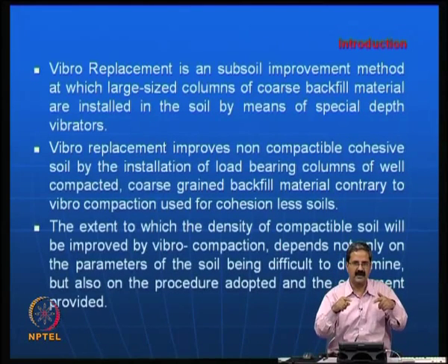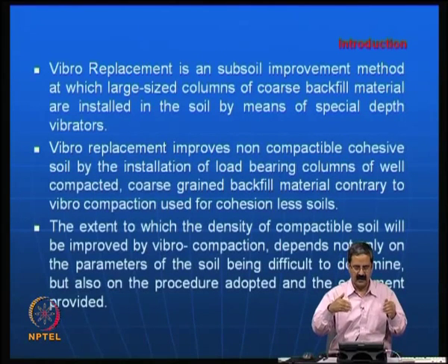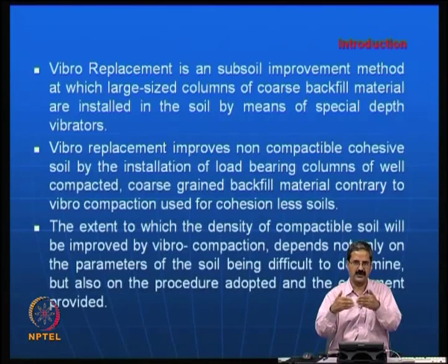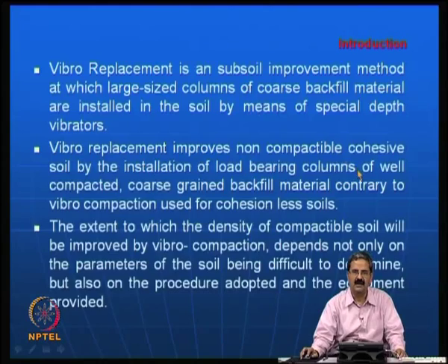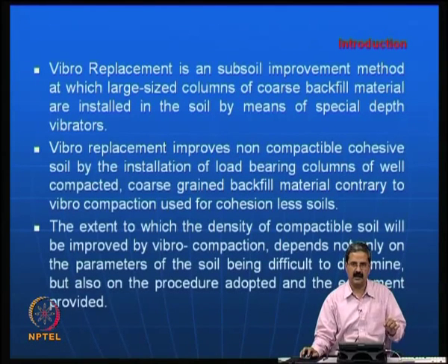We equate it and get the parameters in terms of cohesion, friction angle and so on, and you get an equilibrium equation which will give you what the lateral pressure should be, in terms of the friction angle of the stone column. Something like that is called the limit equilibrium method.